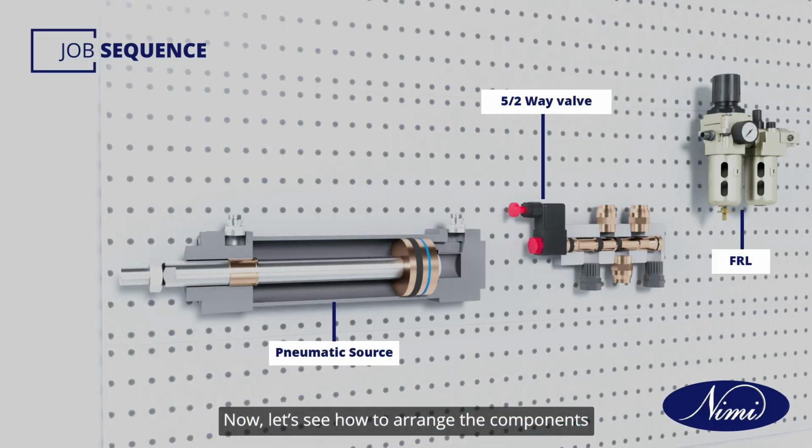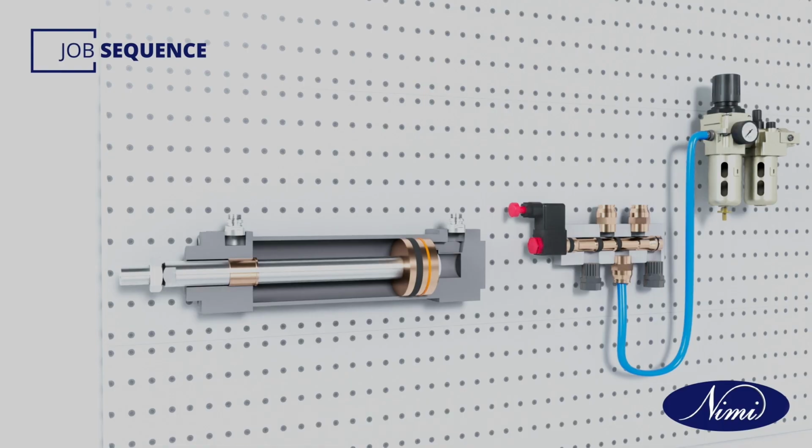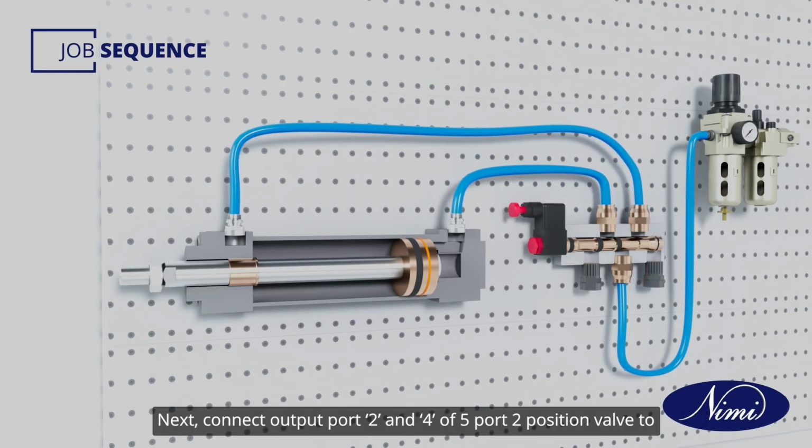Now, let's see how to arrange the components as shown in the circuit diagram. First, arrange the components on the trainer board. Then, connect the source to the FRL and the FRL to input port 1 of the 5-port 2-position valve. Next, connect output ports 2 and 4 of the 5-port 2-position valve to input ports A and B of the double-acting cylinder. Ensure the connections are proper and supply air. Make sure there are no air leaks in the joints.